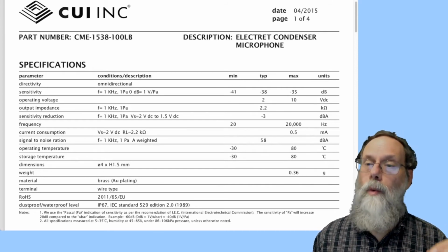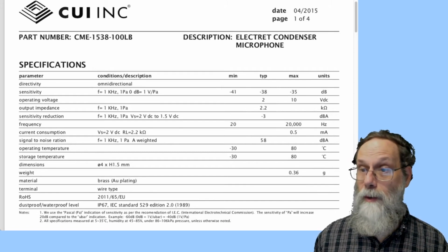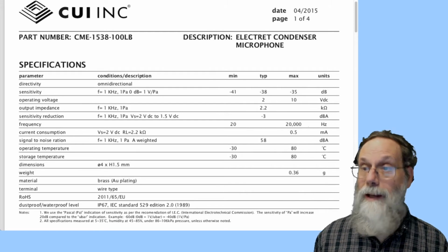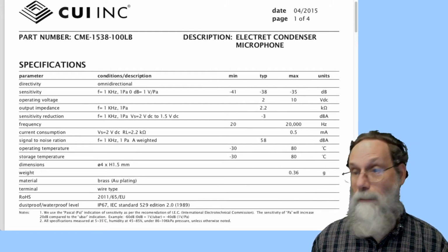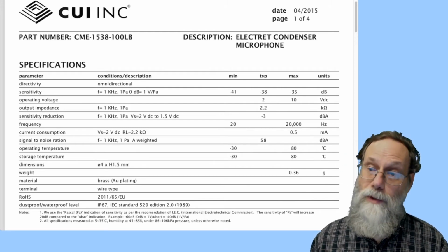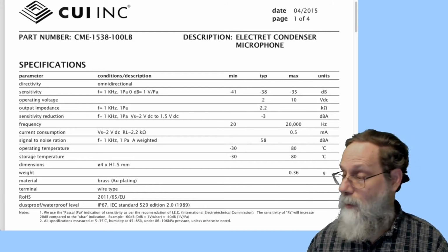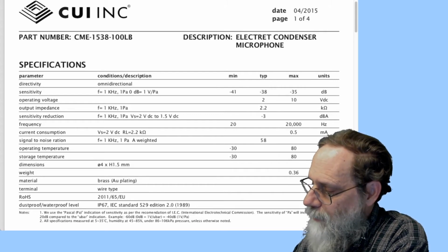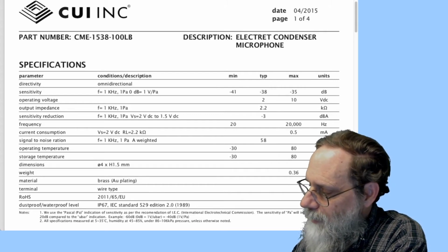But if you look at the Thevenin equivalent of that circuit we were looking at, that Thevenin equivalent does have an output impedance, and the output impedance is just what that resistor R is. So this is telling us what resistor they used for doing the measurement. It was 2.2 kiloohms. So I'm going to write that down over here so when we switch back we can see it.